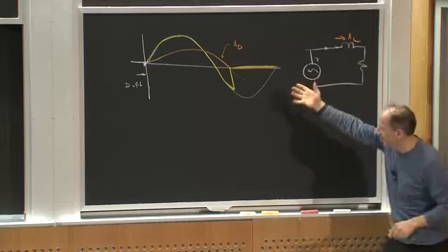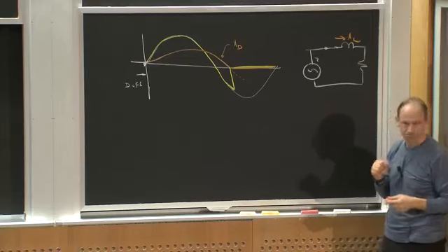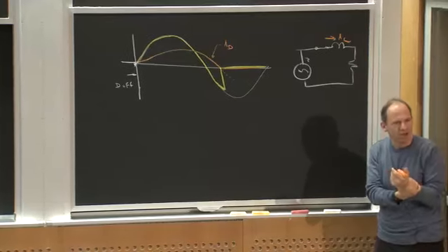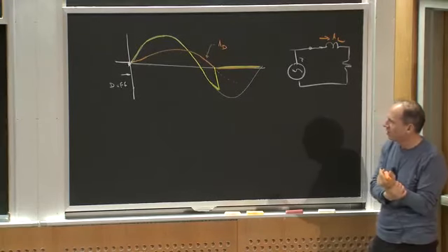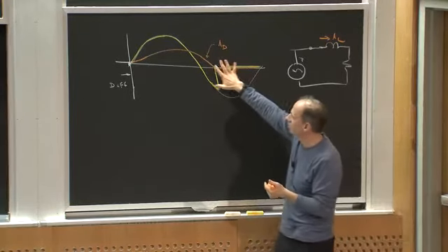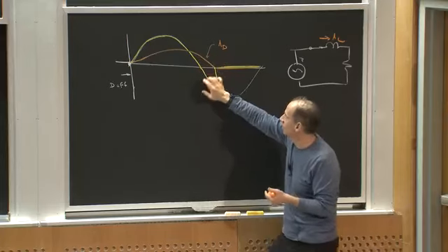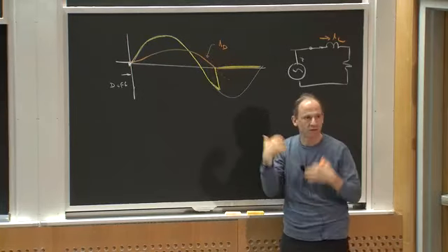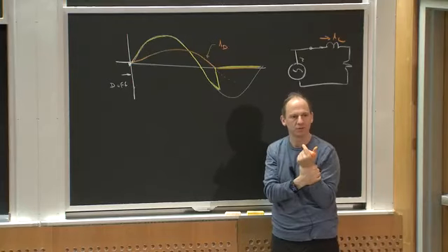Now, what does exactly that solution look like? We can calculate that. It depends on the parameter values. But what we can tell from all this is that at some point, this diode's going to turn off. And it's going to limit the current, and the current's not going to be a smooth, constant current like I might want if I wanted a purely DC output current and voltage.